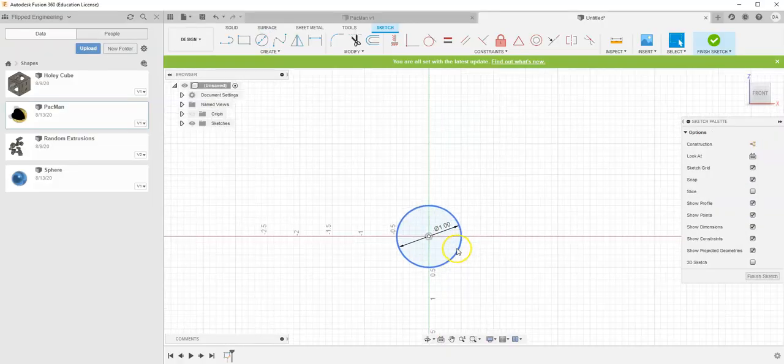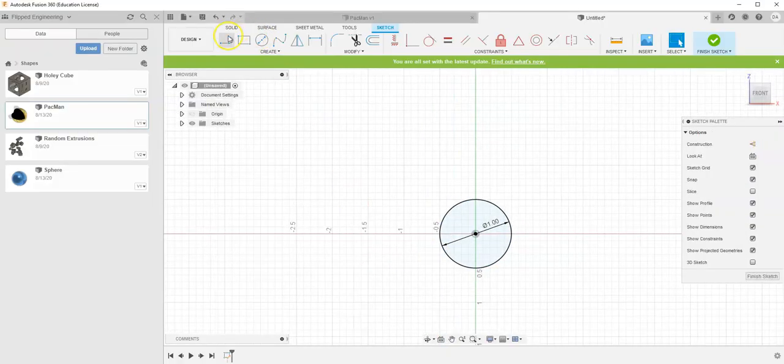diameter. And let's zoom in, grab our line tool, but this time instead of drawing a line through the center of our circle, I'm going to draw it over here off to the left side. And I want to make it a vertical line. Now you'll notice if I get it close to vertical, it'll automatically magnetize as a vertical line. You can even see a little constraint pop up saying it is vertical. And so if I click and hit escape on my keyboard, you'll see this line is stuck vertical.